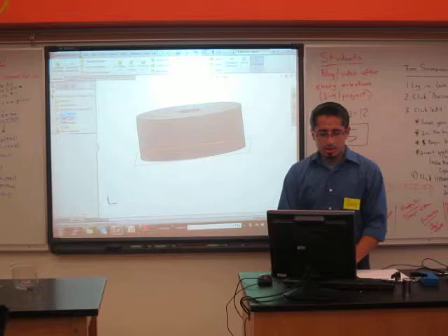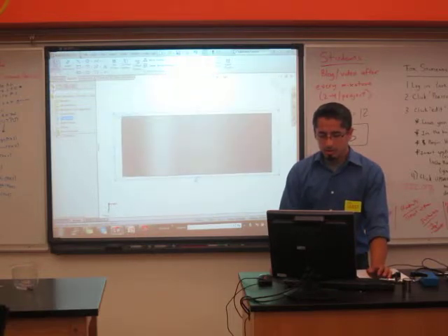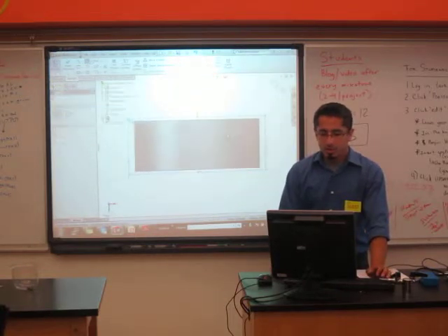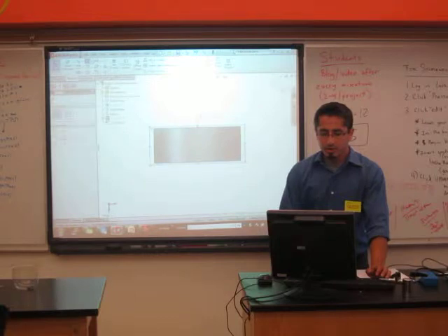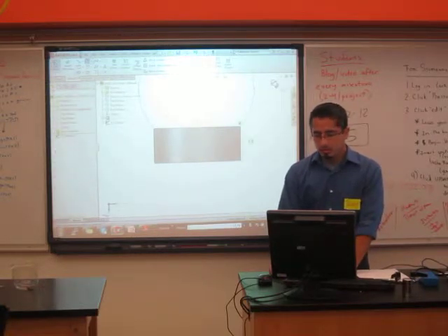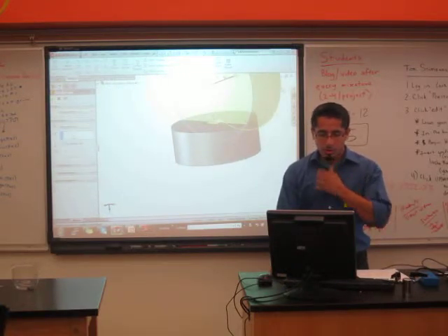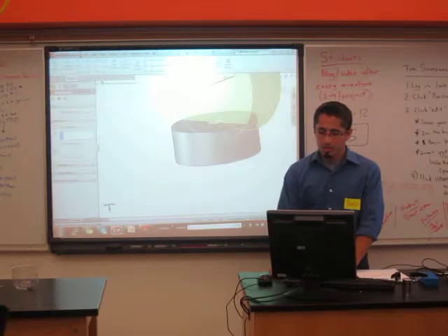Here's the next thing I want to do. I'm going to take the other plane, which is this way. I'm going to do an extruded cut. Let's say I need this to fit over another round cylinder. So you start to learn how these design software work. I'm going to do the other direction, so it's not going all the way through, it's only going halfway cutting through. So I'm going to hit the second direction through all the other way. Okay, let's see what happens.